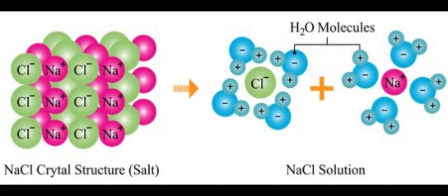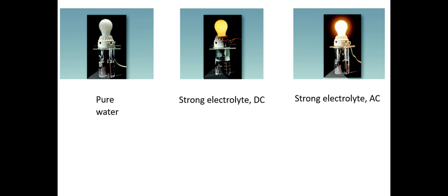Conduction is mostly an AC phenomenon. If the voltage source is DC, the ions will tend to accumulate near the electrodes and conductivity will quickly drop. But if you use an AC signal, then the AC periodically reverses direction, and that prevents ion accumulation at the electrodes, and you can get some significant conduction.